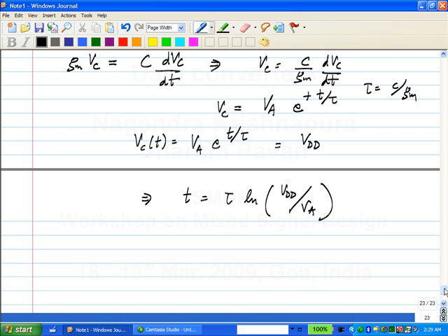All that we have done is reduce the complexity: instead of repeating so many amplifiers, all that we need is one voltage controlled current source. The Gm is nothing but a voltage controlled current source. It's only one voltage controlled current source, right? And now, given time, if you wait long enough, you'll be able to resolve. That band of uncertainty becomes smaller and smaller and smaller. Does this make sense? Okay?